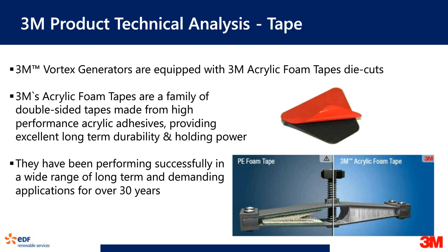Then when you go to an adhesive that is rigid, there's no transfer of energy from the blade overall. So you have two coefficients of thermal expansion completely different, and you put a rigid adhesive in between, then basically the easiest part gives up because you need some flexibility, you need some forgiveness in this attachment so those forces are absorbed and not transferred completely.